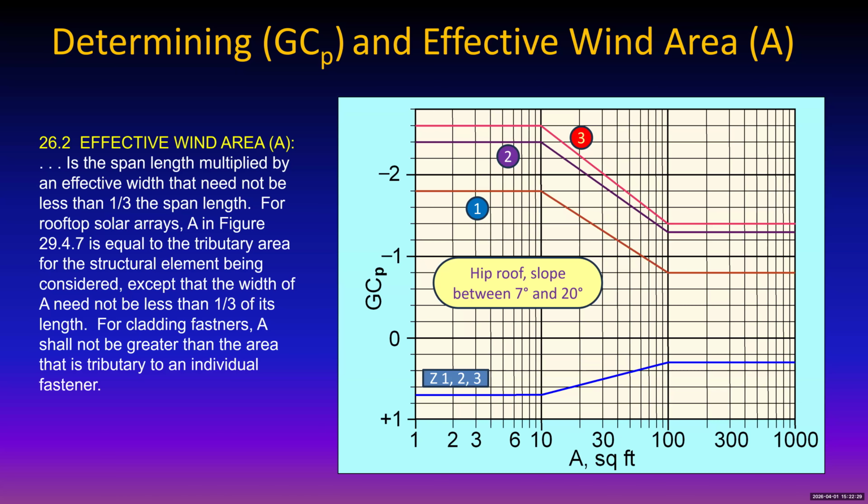So on the other hand, when you're mounting modules in landscape, normally you're not going to have more than about 3 in a row. So that total area is maybe going to be 60 square feet. And it wouldn't be 92 square feet because there are just not enough modules in a row. But here we got 7 modules in a row, so that gives an A of 92 square feet. Okay, so there we go.